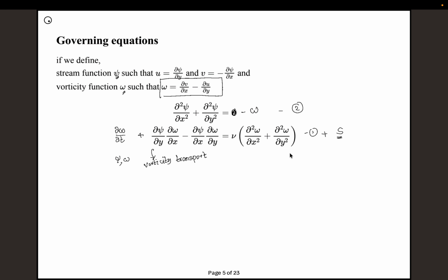So there is nothing stopping us from this, but in order to solve this equation, we would still require the value of omega at t equal to 0, which itself is unknown to us. The problem is usually known in terms of primitive variables alone. If it is a steady state problem, if you know that the problem has a steady solution, then we can neglect this term and go ahead and solve this particular problem. But otherwise, it's very difficult to get the values of omega for even the boundary conditions or initial conditions anywhere, because omega is something that we eventually compute in the post processing for most of the problems.